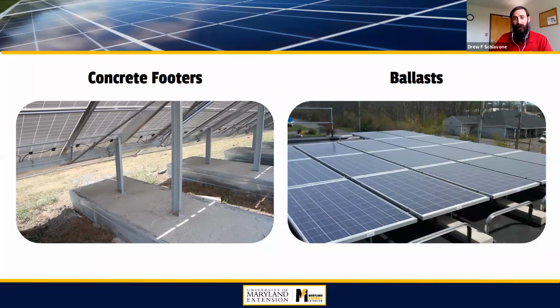Ballast as well. If you weigh it down with blocks or something like that, you'll see that used on flat roofs. There's benefits. You don't have to penetrate the roof. You could use ballast on the ground as well, but you don't see it as often.